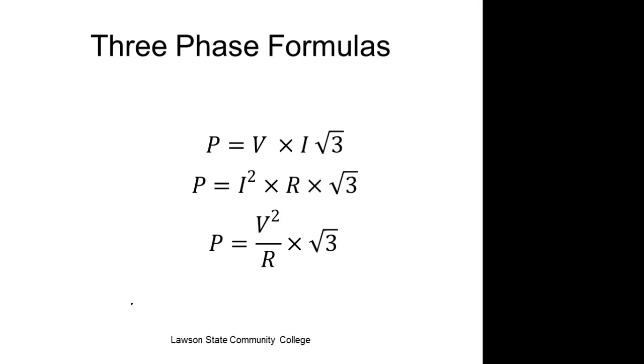We don't double it, we get 73% by adding another wire. So this is why when you look at these high power lines, you'll see 3 wires running. That's 3-phase. If you see 2 wires running, it's what? Single phase. If it comes into your neighborhood, it's probably single phase. But somewhere that line is going to hook up to 3-phase power.